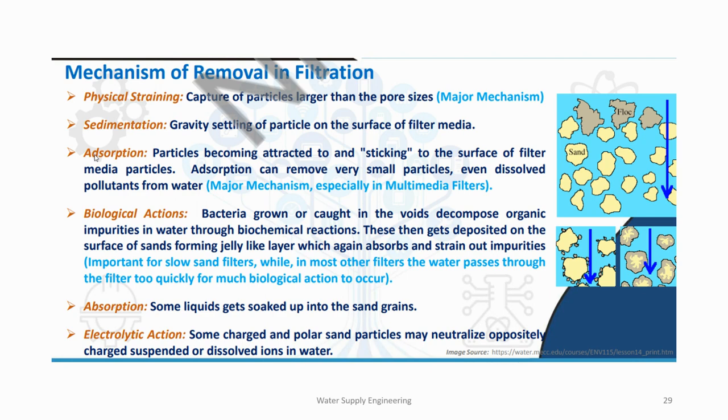So it is moving inside into the sand grains. Then the last one is electrolytic action. So here, some charged and polar sand particles may actually neutralize the colloidal or suspended particles which have opposite charge.